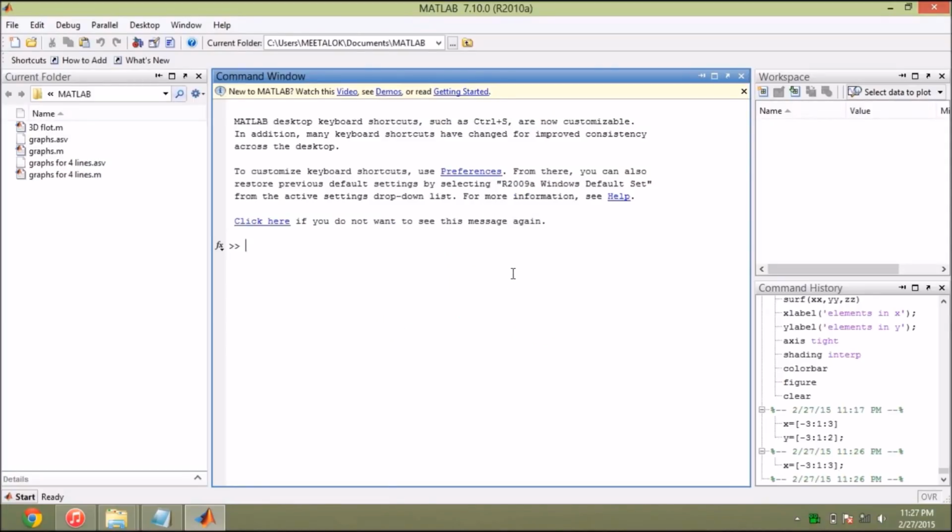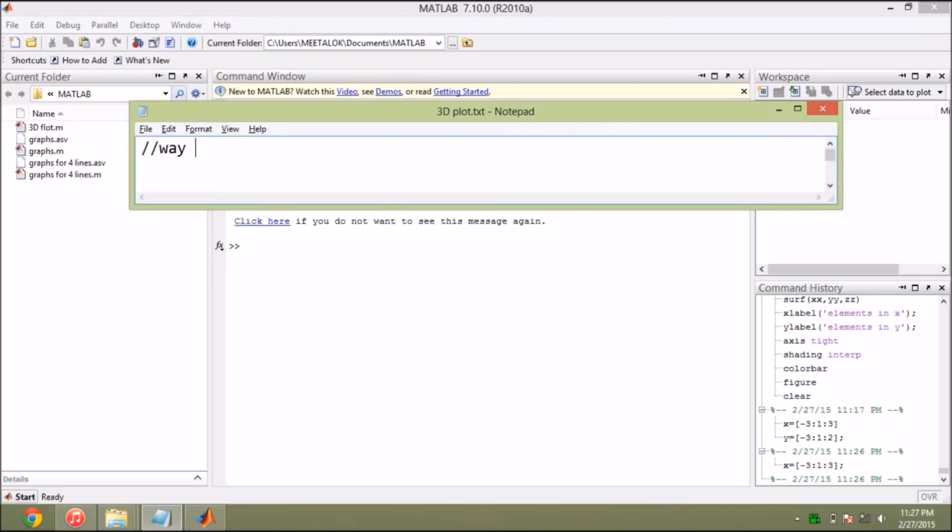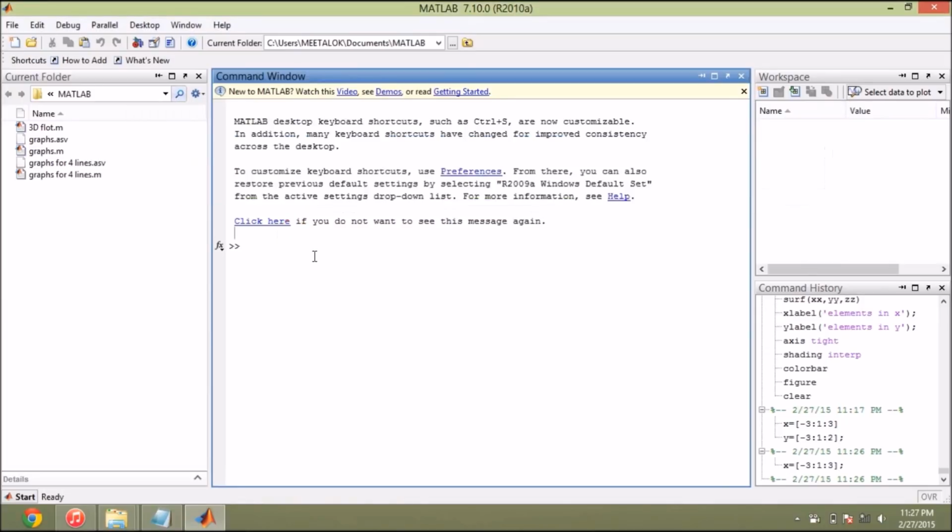To one more exciting show of MATLAB, in which we are going to plot a 3D plot in MATLAB. So, the way to plot a 3D plot in MATLAB. At the first stage, we will define variables, let's say x, y, and z. For defining x, let's take its coordinates as -3, 1, and 3. So in MATLAB, we will write x equal to -3, 1, 3, hit enter.